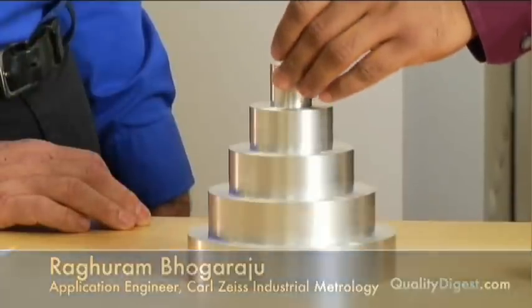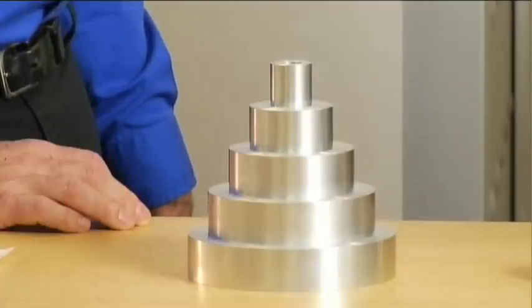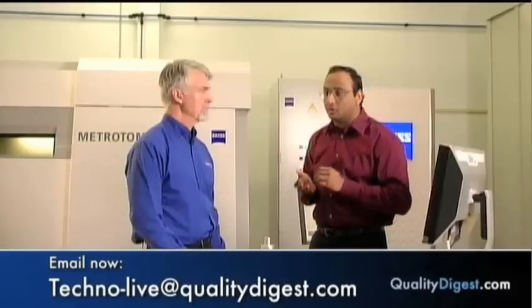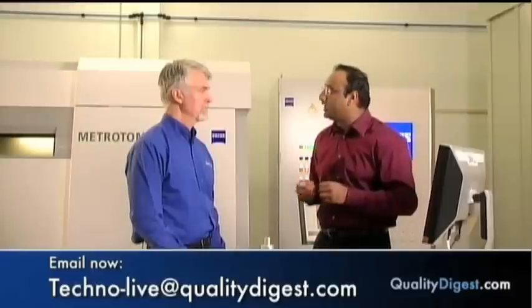So what we at ZEISS do is have our own internal algorithms during the data reconstruction process that go into every one of these individual pixels, or what we call voxels, and actually find the true edge for the part. That gives us the most accurate data sets that come right off the machine. So the data is ready to do any calculations when it comes off the system. There is no scaling, and absolutely no converting it into any other formats.